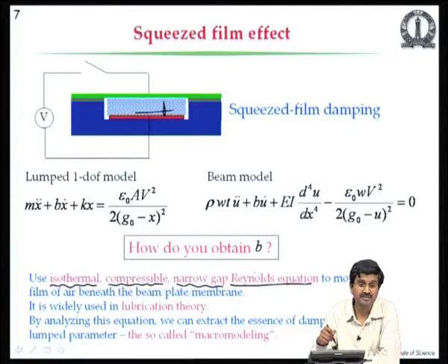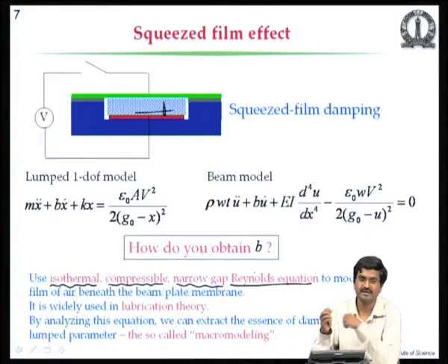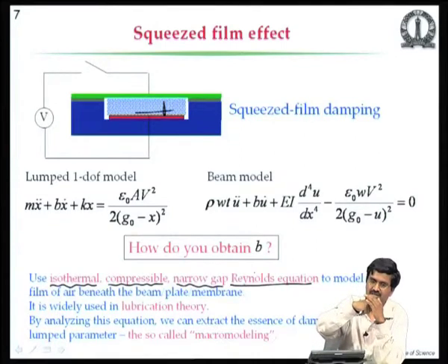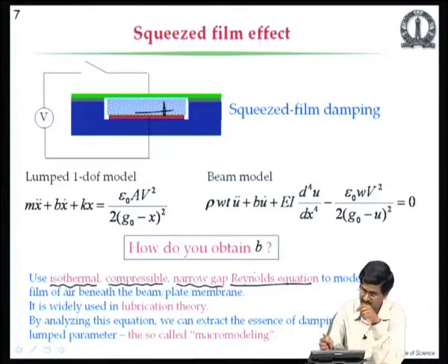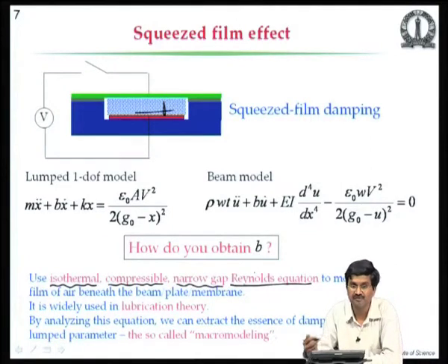And this particular equation actually comes from lubrication theory. So, if you imagine a journal bearing where there is a fixed shaft, and actually not even fixed, they relatively rotate, the journal and the shaft, in between there is a narrow gap, and if you put oil in that narrow gap, the oil is getting squeezed, and that is where this Reynolds equation is very useful and very well developed.